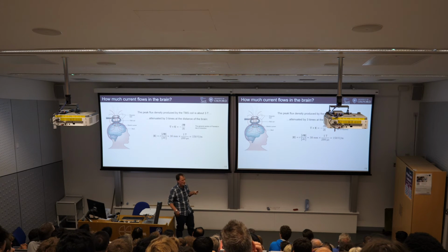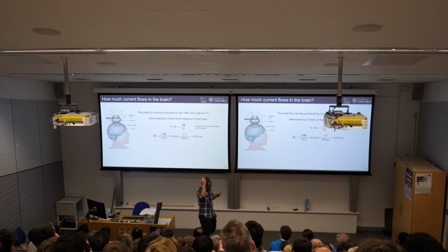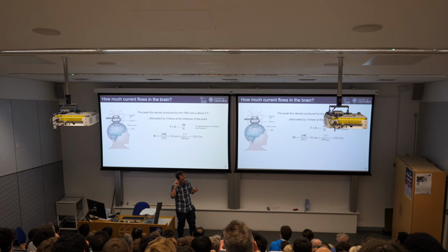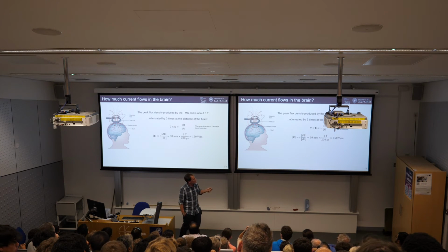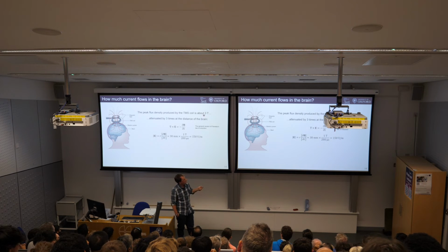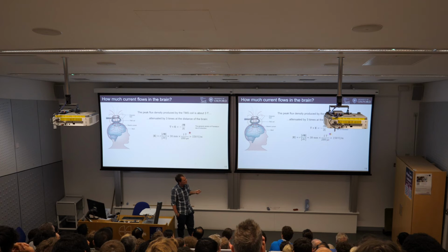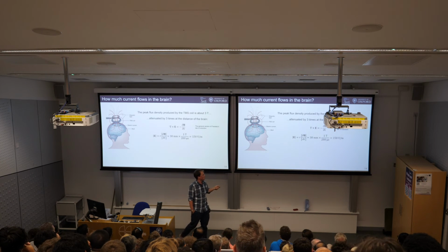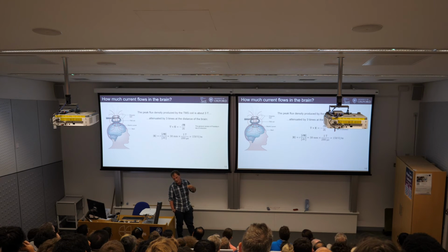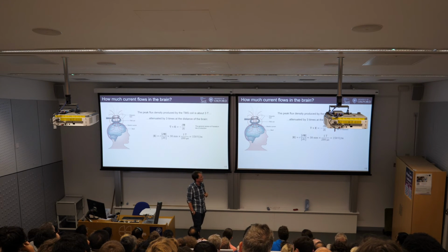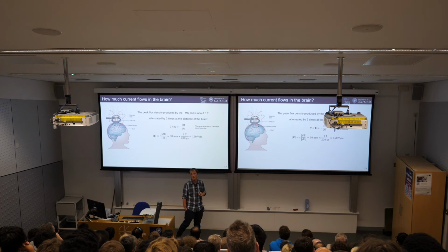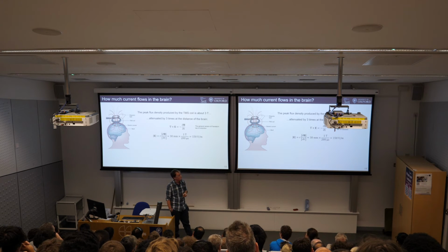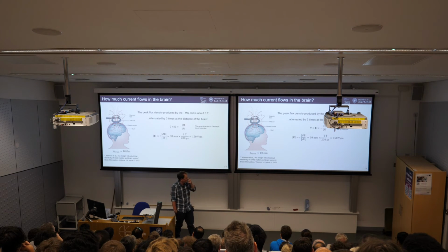So the distances involved are about 30 millimeters between the coil and the brain; the field goes through your skull, through various bits of tissue, and then actually starts interacting with the brain. And we've established that we had a 3 Tesla peak flux density at the coil, but this is attenuated to something like 1 Tesla by the time it gets to your brain. The pulse length is about 200 microseconds, and then we can very approximately work out the field strength as 150 volts per meter.